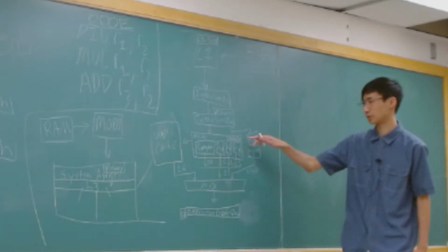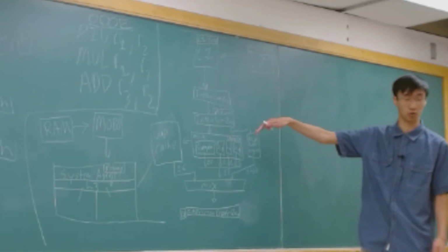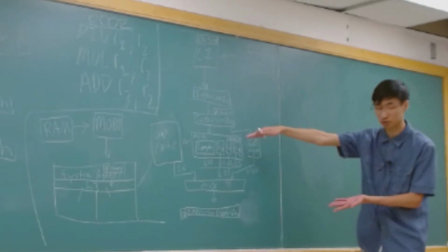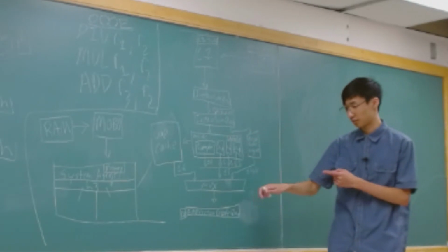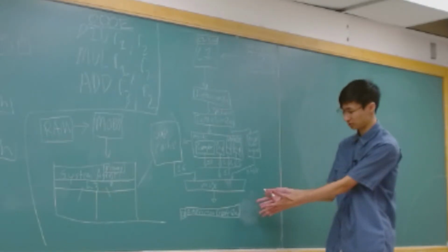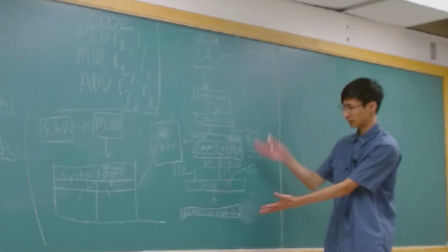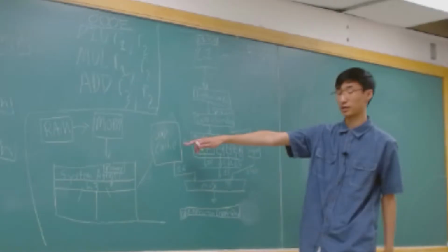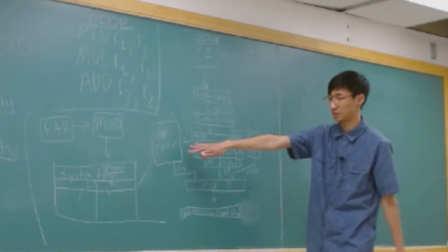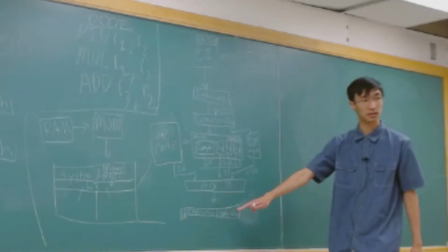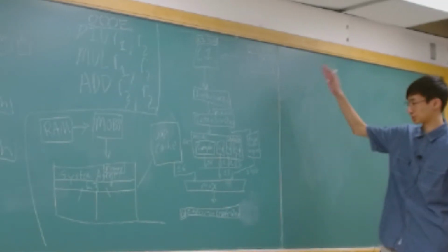So microfusion happens in the decode, or somewhere in the decoder, and this makes no sense to put it here, because we want to save some space in the micro-op cache sometimes. So we'll do microfusion to save space in the micro-op cache. We'll save space in the number of entries throughout this CPU.